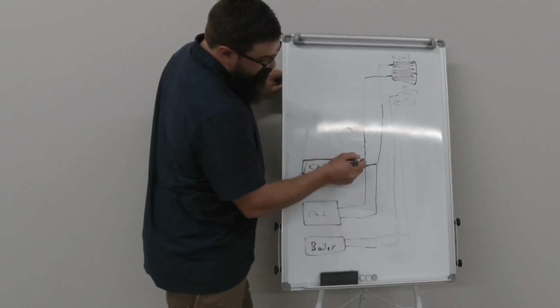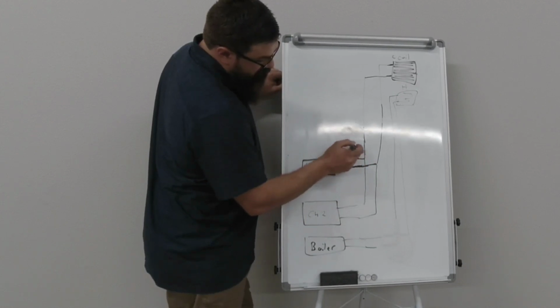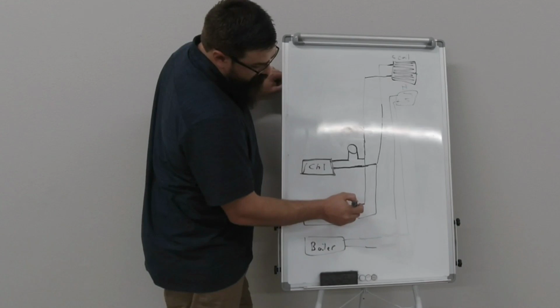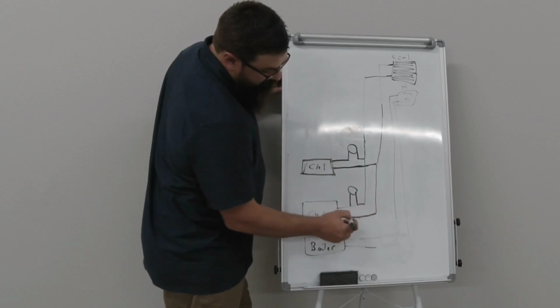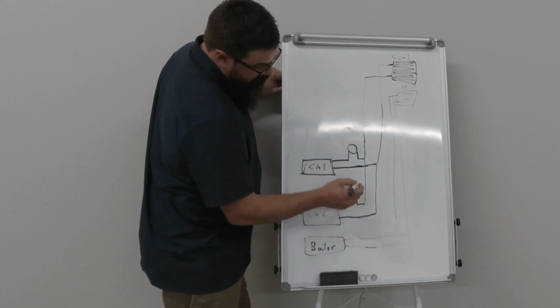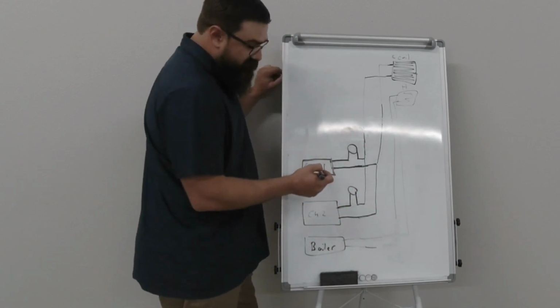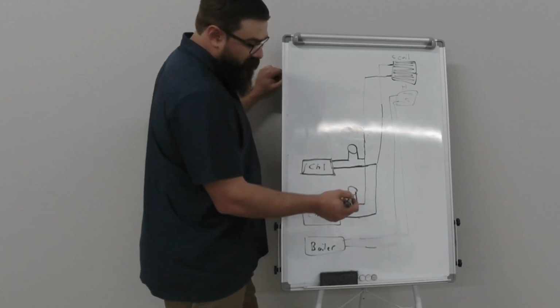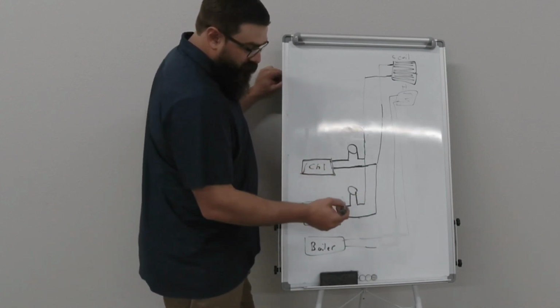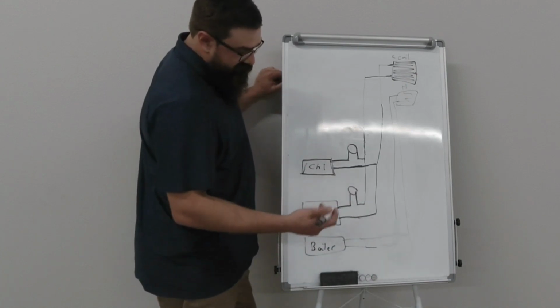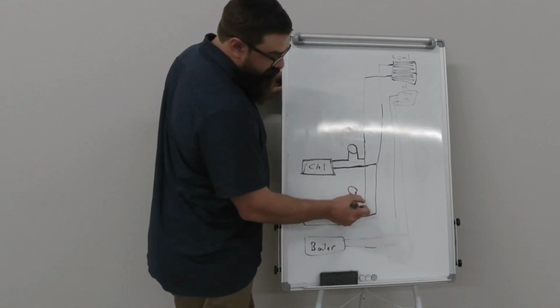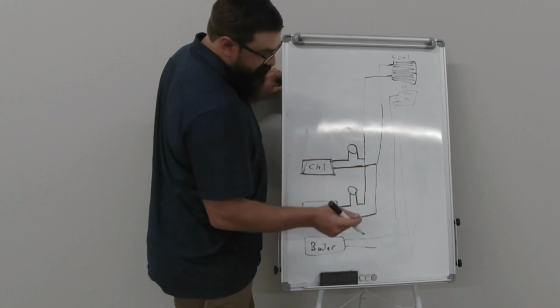you would have a pump for each one, and then that pump is controlled either through the BAS along with that chiller or through the chiller directly. So we just start the chiller and it starts the pump, or we start the pump and it starts the chiller, however it's wired. It can be done many, many ways.